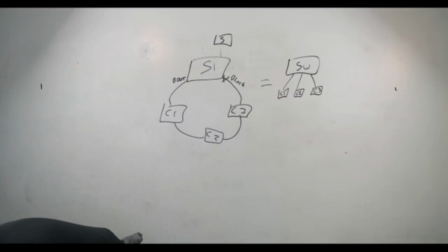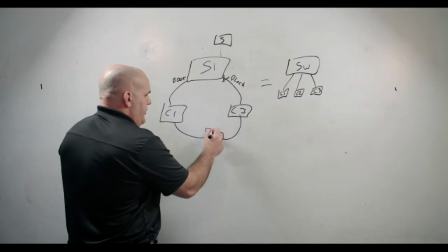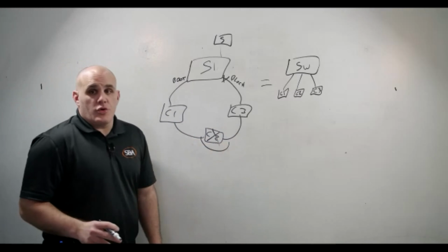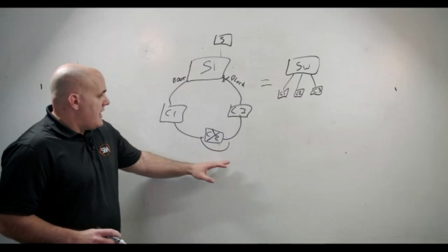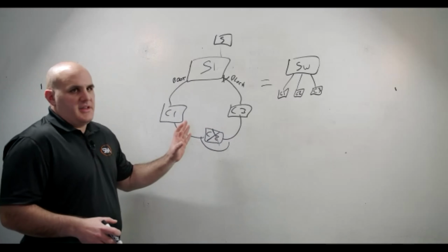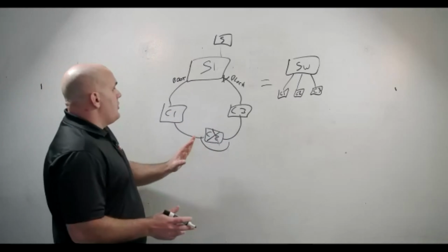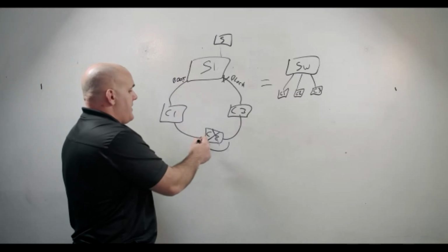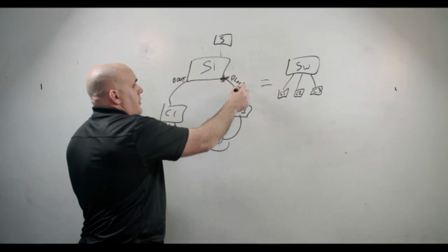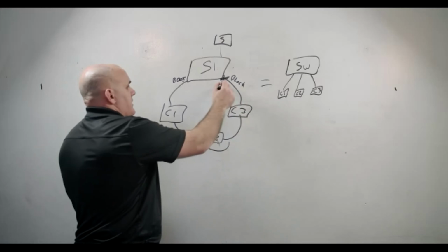The problem with that is that let's say this controller goes down, controller 2, boom, loses power. This IP message is not going to pass through. Now, manufacturers are working on passing this by using some switching that would automatically fuse the connection to pass through, but a lot of products don't have that right now. So what happens then is this root port says, oh crap, there's now a break. It's not a ring anymore. And so it stops this blocking port and opens up this blocking port since there's no longer a loop, and it allows traffic to flow.